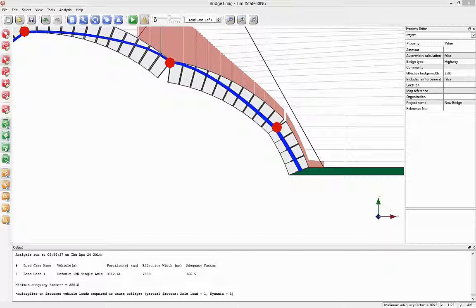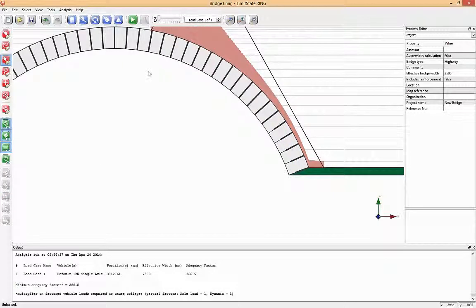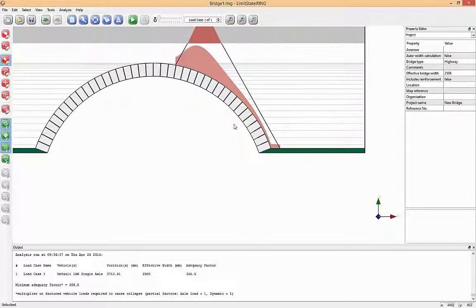Okay, second one: I've got several bridges where the patch repairs with stronger brickwork. Can I take advantage of this? If you've got a bridge that's 100 years old, then very often much of the masonry is original, but some parts of it are not. Sometimes you find that a good region of masonry, for example around the springings, has been replaced. So in this case, let's keep this example.